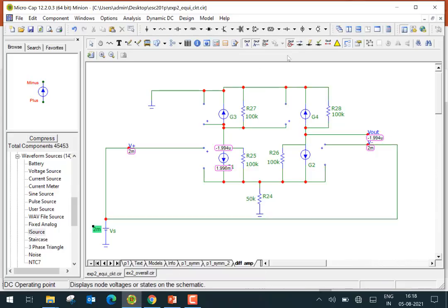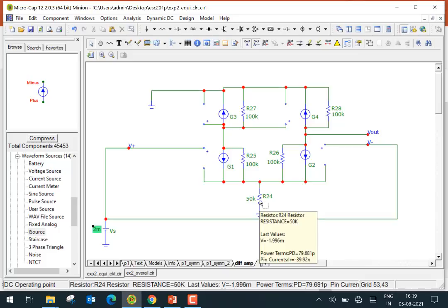So now because this voltage and this voltage are the same and the lower half of the circuit is symmetrical, we can use symmetry, the kind of things that we had seen in the previous example here. For example, we could make the circuit more symmetrical by taking this 50 k ohm resistor and splitting it into 2 resistors here.